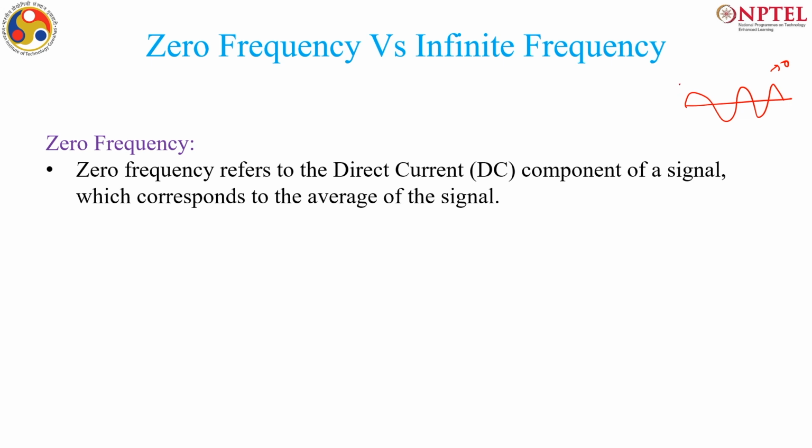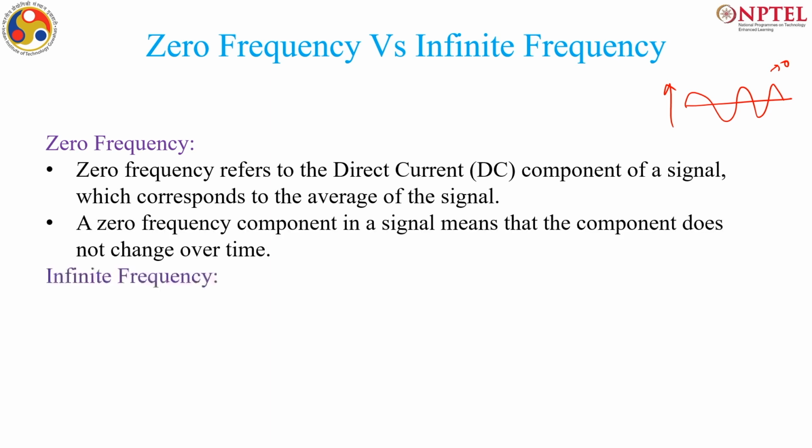But if we bias the axis such that we add something to this signal, then the signal shifts vertically up, which I have already discussed in the time domain, that amplitude shifting. So, that is introducing this DC component or DC frequency to this signal. If you have a DC frequency, that means that the signal has a bias and it does not have a zero mean. And zero frequency, because the definition of frequency says that it is the number of oscillations in a second or unit time.